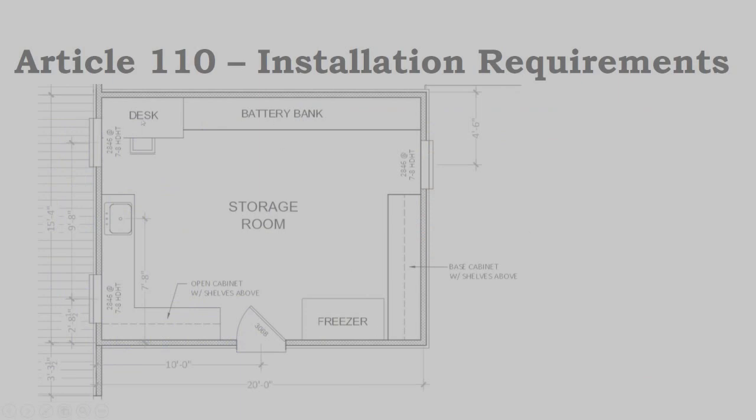Well, I guess we could use the back wall. And so this essentially says, where are we going to locate our inverters and our batteries if we just want to use a single wall? Can we put them here, or can we put them here? Well, we don't have enough space along this wall. We'll have to use this wall instead, get rid of that desk and put the batteries along this wall, because that's the only wall that has enough space. Alternately, we could catty-corner them, get rid of this doorway, and put them on a corner here and a corner there.